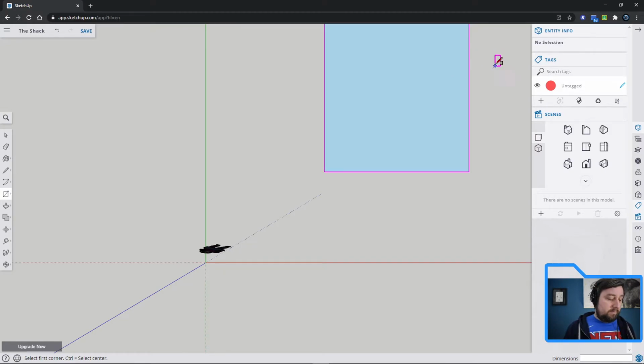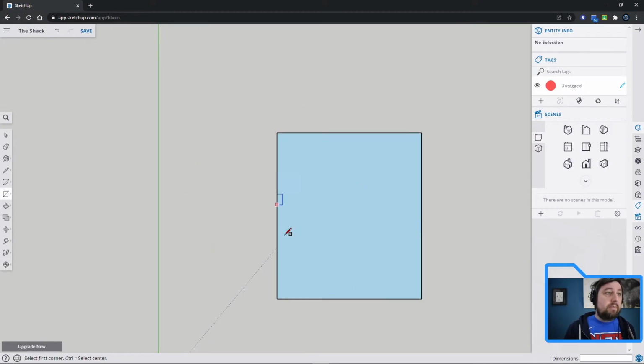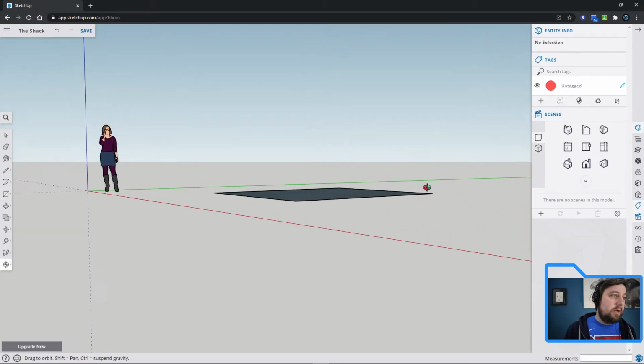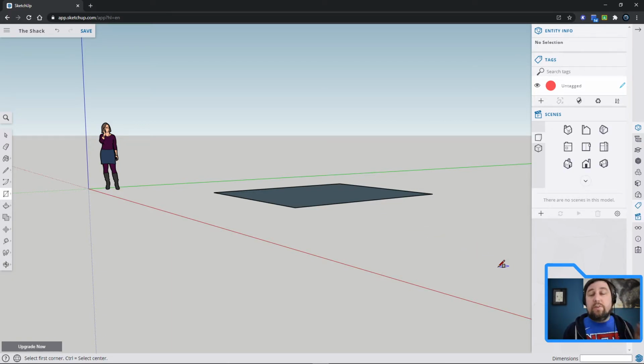And you'll notice, with Shift and the mouse wheel, it made a rectangle and it's got a color on the inside, shaded. When it's shaded, that means it's a closed shape. That means we can mess with it. All right, now that I have a rectangle, I'm going to click down here at the isometric view. And you'll notice I'm flat on that plane. I'm not at an angle. It's not floating anywhere. It's not crooked. The reason is I made sure it was flat. This shows it made a blue rectangle. You'll notice, look, I can make it red. This would be on that plane there, and so on and so forth.